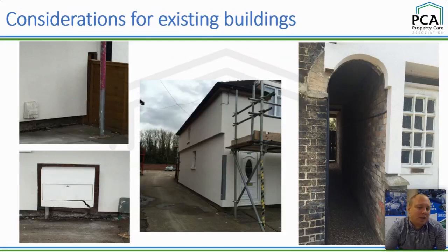My particular favourite is that top left-hand corner with the timber fencing. So you've got the timber fencing with a life expectancy of what, years, and then you've got the insulation, which is guaranteed for 25 years. So you've got that cold bridge going, where they've cut around the insulation. It's just horrific, isn't it? But there we are. So I'm going to bring this back, hopefully.